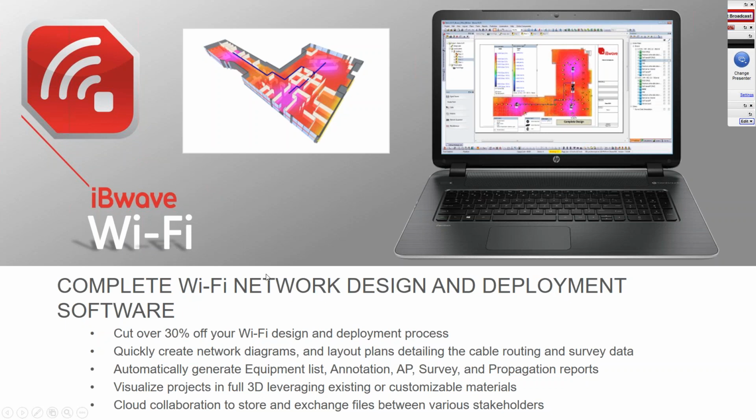To do this, it's actually quite simple. You can take AutoCAD plans, import them, and automatically assign materials to the different layers. You have the ability to draw those walls manually, of course, and this really gives you the functionality to choose whichever one is more optimal in your case.